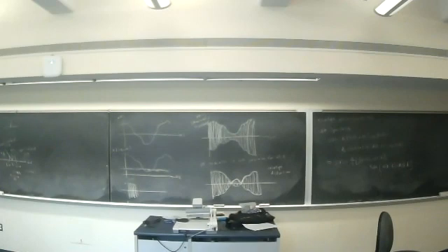For AM radio, we said it goes from 660 up to 1600 kilohertz. They're 10 kilohertz apart, so that determines how many AM radio frequencies I can actually have. Again, radio frequencies are reused, right? You can hear maybe 1200 kilohertz here, and you go out to California and there's a 1200 kilohertz station.